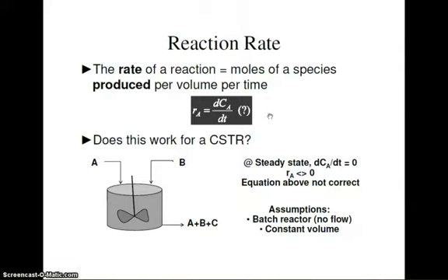You probably recall that a CSTR is a continuous stirred tank reactor, or a mixed flow reactor is another term that's used. And the idea is that it's completely well mixed, so there's a tank, it has an impeller or some other way of stirring, and it's well mixed at all times. We feed in reactants and we remove products and any unreacted reactants as well. And generally these reactors can be thought of as operating at steady state.